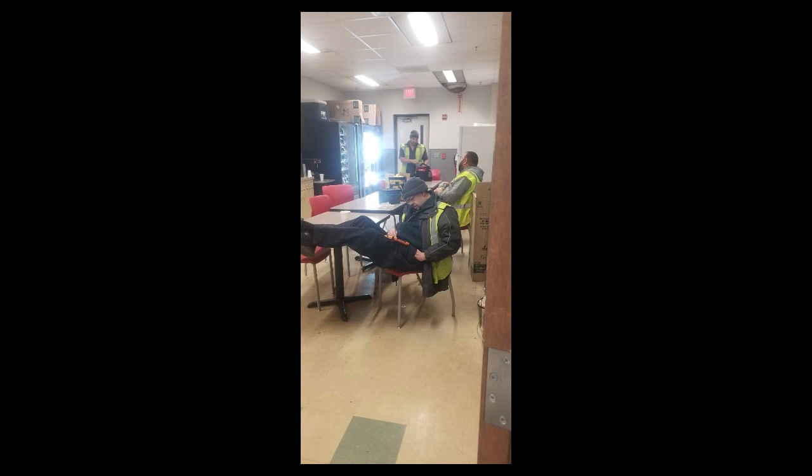53. A DME antenna should be installed on the aircraft in a position that will not be blanked out by the wing when the aircraft is banked. 54. When installing a DME antenna, it should be aligned with the center line of the airplane. 55. Aircraft antennas must be grounded to the airframe. 56. What is the primary purpose of an autopilot? To relieve the pilot of control of the aircraft during long periods of flight.